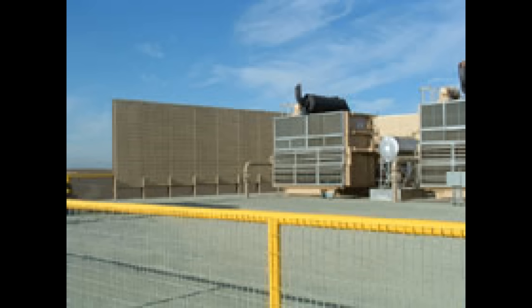This is a large barrier wall. It could be a combination barrier absorber. For instance, if it's a barrier, you're going to be reflecting that sound back to our right here. And there may be, probably is, a building there, where you would then get reflected sound going back the other direction. So if you add absorbing material in there also, you'll get less reflected noise. Or you put absorbing materials on the building, the other reflective surface.